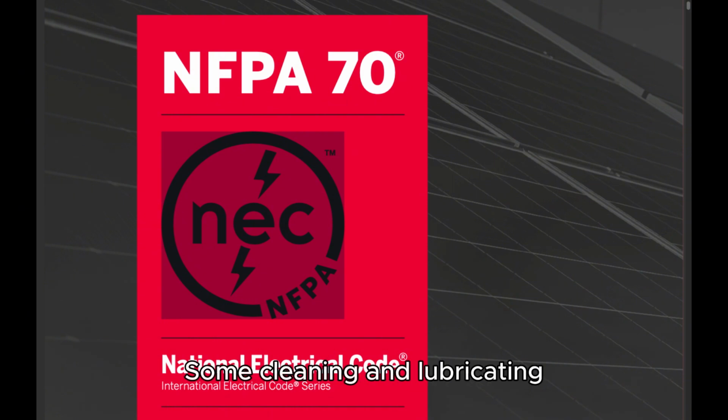Informational Note Number 2: Some cleaning and lubricating compounds can cause severe deterioration of many plastic materials used for insulating and structural applications in equipment. Equipment not identified for outdoor use and equipment identified only for indoor use, such as dry locations, indoor use only, damp locations, or enclosure types 1, 2, 5, 12, 12K, and/or 13, shall be protected against damage from the weather during construction. Informational Note Number 3: See Table 110.28 for appropriate enclosure type designations.